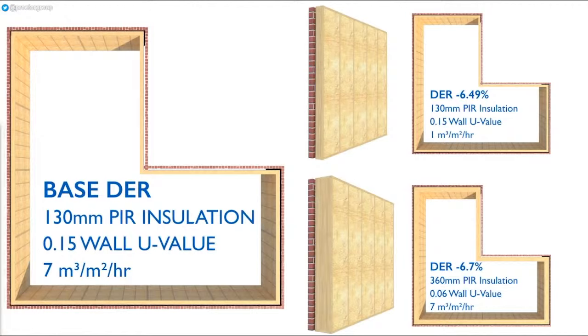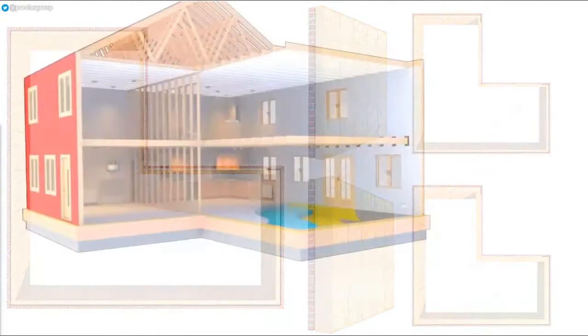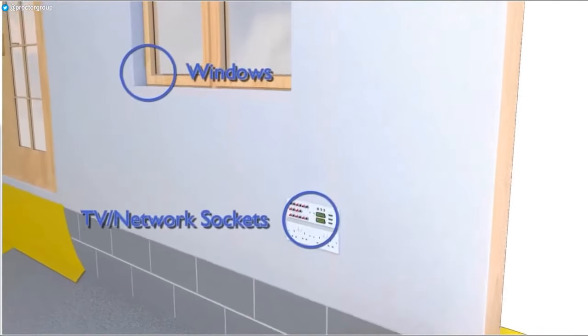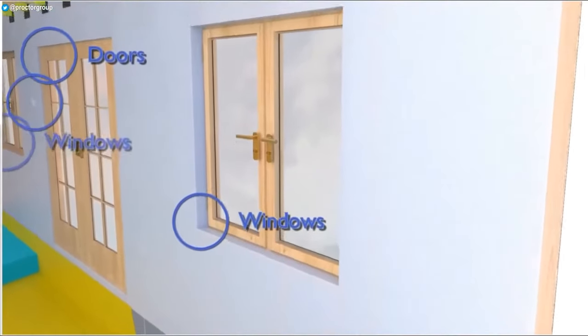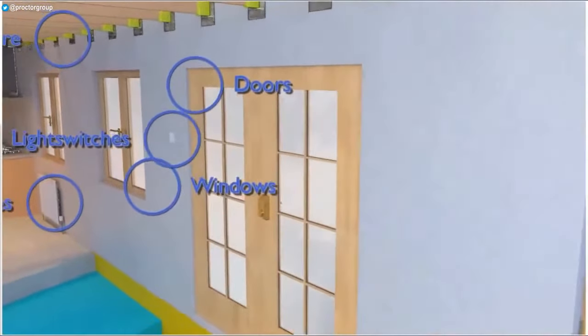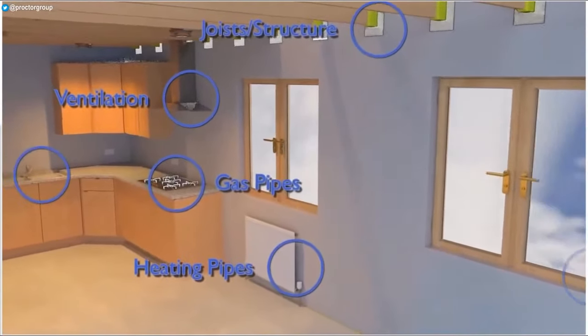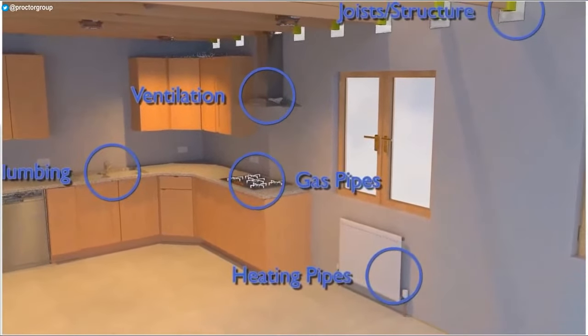While this reduction in air leakage sounds dramatic, by using the wrap-tight air barrier membrane, adhered to the external face of the sheathing, and taking care to ensure it is well installed around windows, doors, and sealed to any other penetrations, this is not difficult to achieve in practice. The primary advantage of wrap-tight isn't necessarily improving the airtightness result, but making arriving at that result significantly easier, faster, and less affected by the actions and skills of installers.